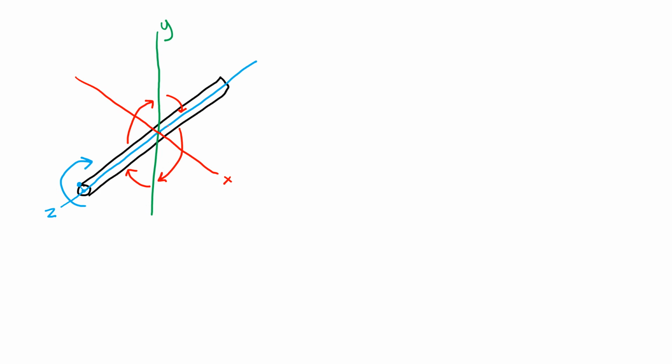So from the center point to the farthest point of distribution of mass, this distance is much longer than it was in the z-axis. In this example, because the rod is oriented the same on the x-axis and the y-axis, whether you rotate it about the x-axis or the y-axis, you'll find that the moment of inertia is the same. The most common example of mass moment of inertia are figure skaters and how they bring their arms close to their body in order to increase their rate of spinning.